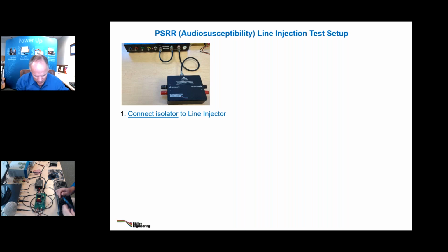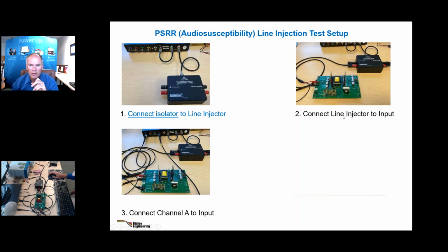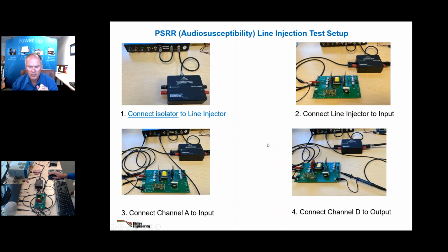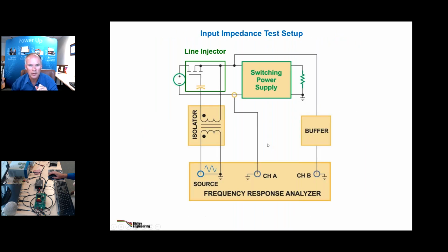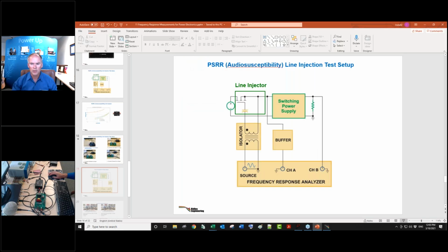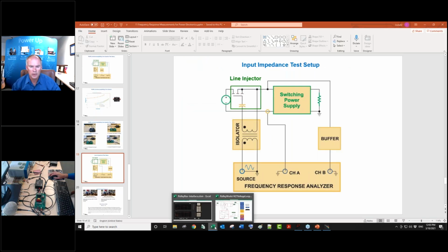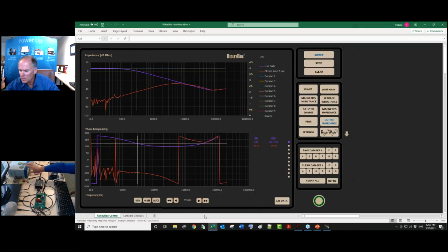Okay, so power supply rejection ratio now from ground to the input pin. We're officially at the end here, but let's measure it first, open loop, since that's what we got here. Open loop. Here, turn on the power supply.